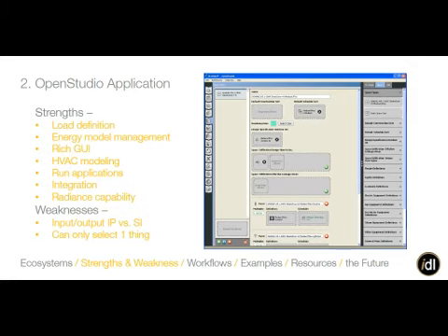It's doing loads modeling. With this you could do a lot more in terms of the detail of passive systems, and also in terms of running different scenarios or looking at the loads throughout the energy analysis period, throughout the weather file period versus the design days, and also trying to come up with different ways to slice that up to do right sizing and stuff like that. So you just get a little bit more information if you handle loads here.